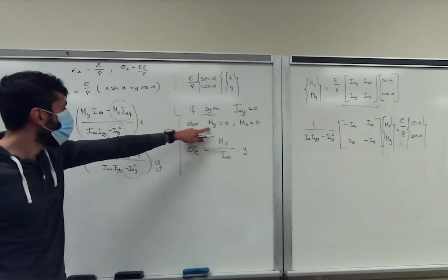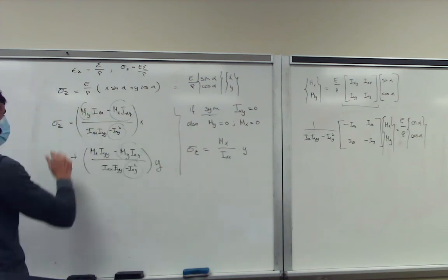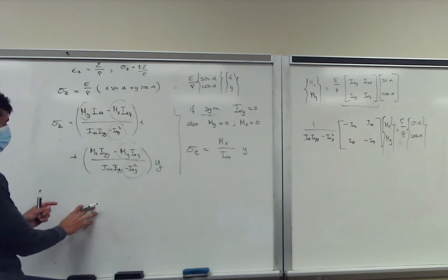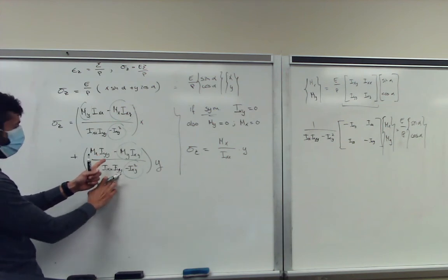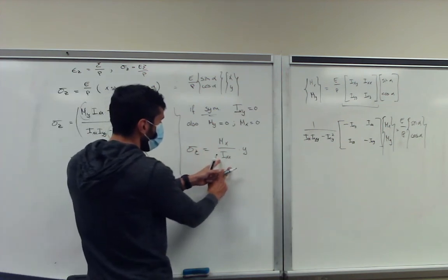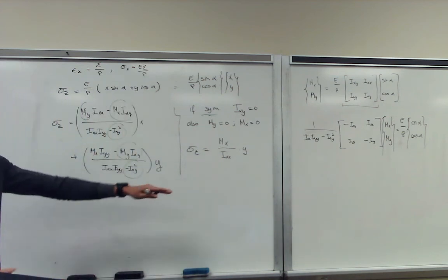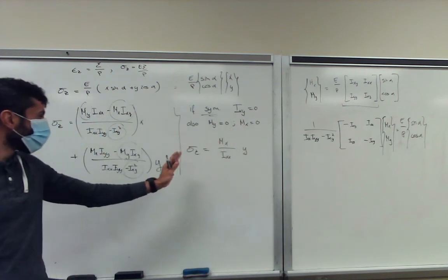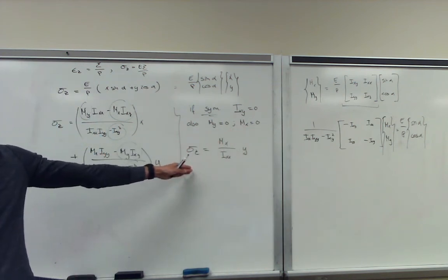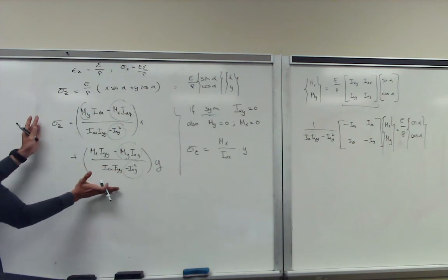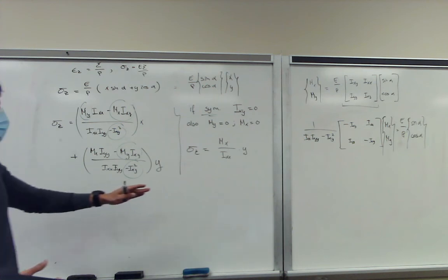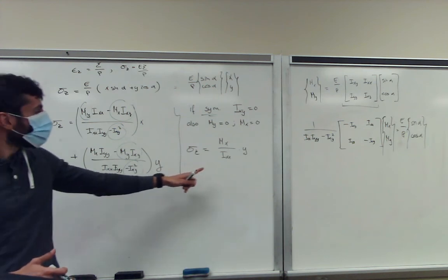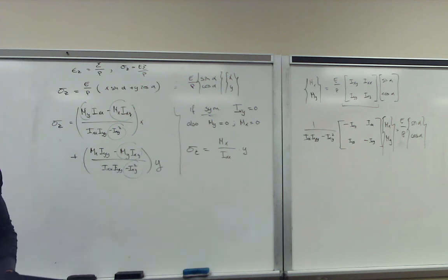Now we also said there's no moment around y, so this drops as well. It's equal to 0, so this whole x term disappears. And here you can cancel out, so you get your original Mx over Ixx multiplied by y. And that was the first equation that we derived. Therefore, I think the -1 comes to here. So basically now you have a uniform equation set. This is your complex, most generic set of equations. Based on assumptions about the cross-section and applied loads, you can always reduce to your given symmetrical loading condition.